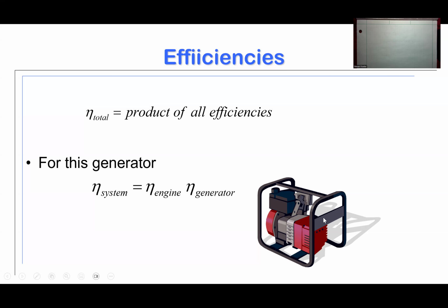Then we've got an electrical generator turning some magnets around, pushing electrons through coils, which then pushes electrons through my wires. This generator portion is only going to have a certain amount of efficiency, maybe 60% ballpark. So overall, you might have a 24% efficiency, because you have the efficiency of the engine multiplied by the efficiency of the generator. They're both less than 100%, so your overall output is going to be even less. Every time you stack components together, you end up with less and less efficiency.